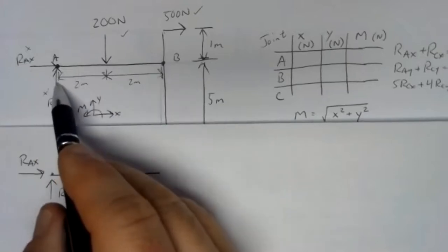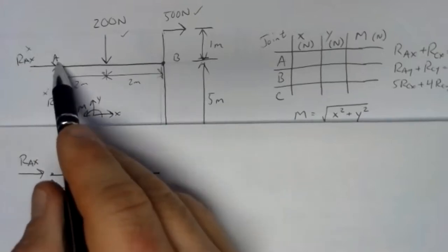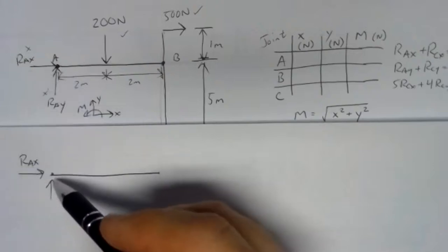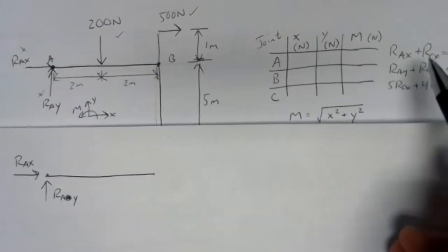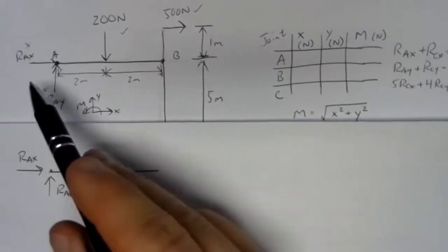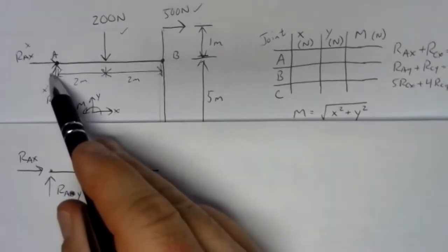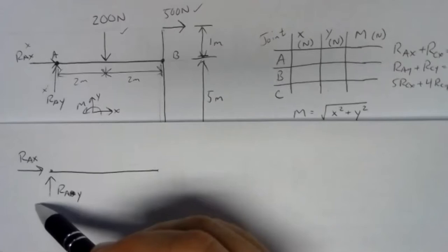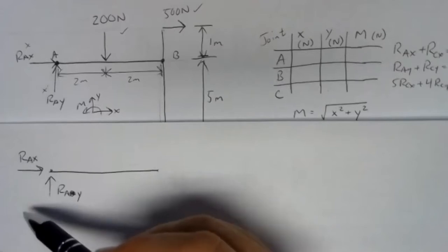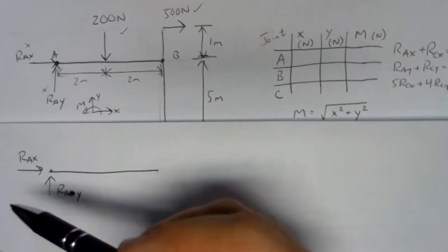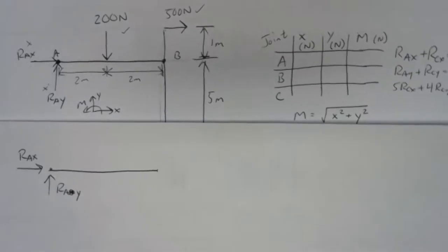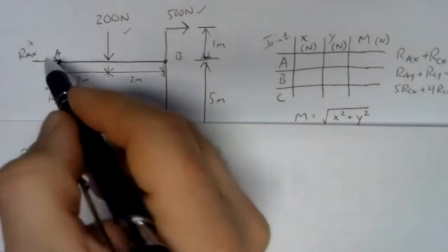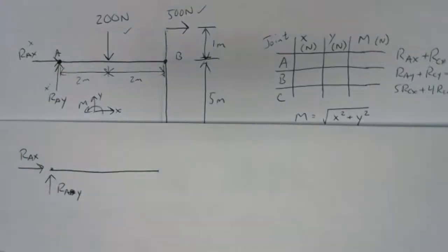If you've already made assumptions about those arrows for a joint like A here, keep the directions the same, because these equations over here were built based on these assumptions and those directions. If you change them, you'll get values that have a different set of assumptions associated with them. Now, there are some times where we do have to change directions, but that never applies to the external supports. It's only the internal joints where we might have to do that.